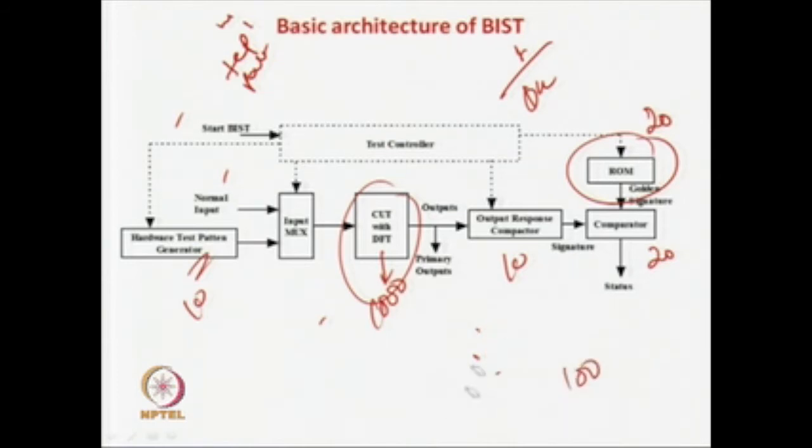So, you can think that for 100 test patterns, maybe there were 10,000 test patterns for offline testing. Now you have got only 1000; you selected very good or efficient test patterns which detect more faults, and you generate them with the random pattern.